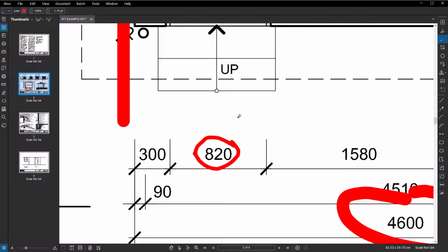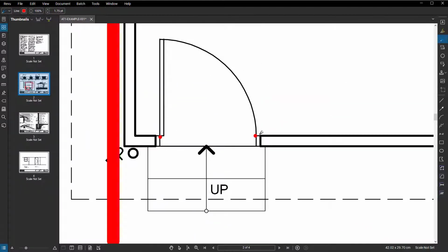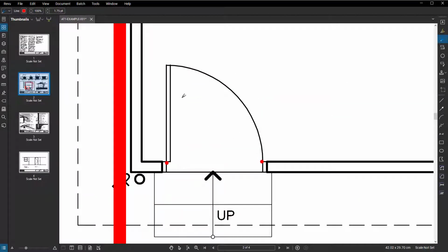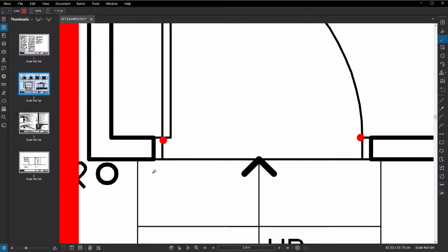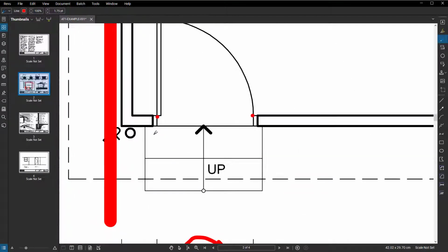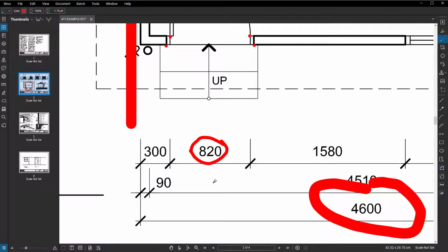So when you see a door size, even when you go to Bunnings and you'll see 720, 820, 920, etc., that's referring to what is known as the door leaf, which is this component here. That is the bit that you grab onto and you open. The door frame, which is denoted by these two rectangles, is a separate size. So when you dimension an opening, you're going literally from wall to wall of the opening.